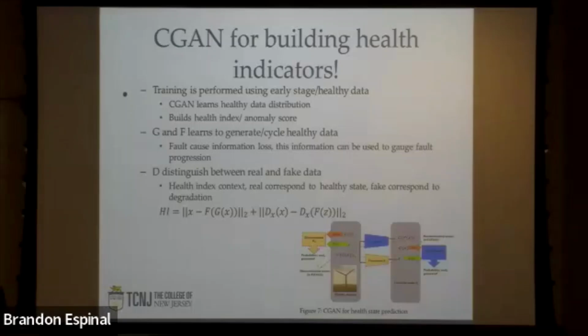And one of those things is power output. That's one of the parameters that you're measuring. If there are discrepancies between what the translation says the power output should be versus what it actually is, that's some indication of a failure in the wind turbine and is something to be investigated by a person. That's a sign that someone actually needs to go out there and look at it. And that's useful for a wind turbine company because they don't have to send someone out regularly; they already have health indicators saying when you need to go inspect this wind turbine.